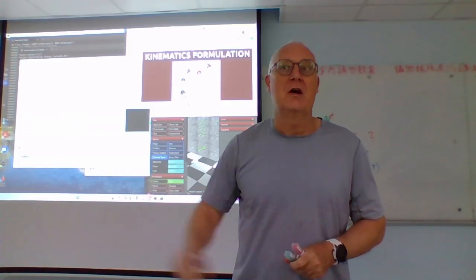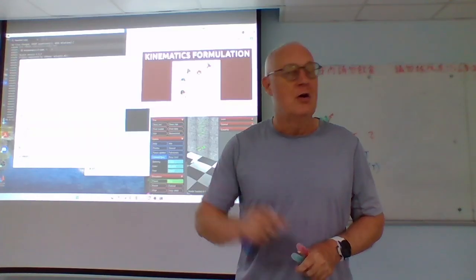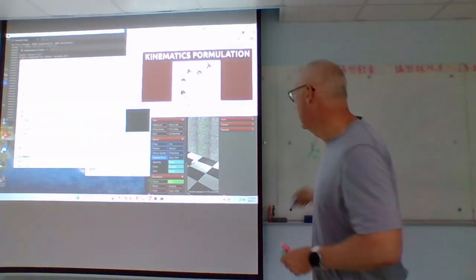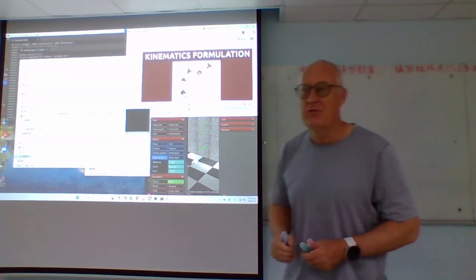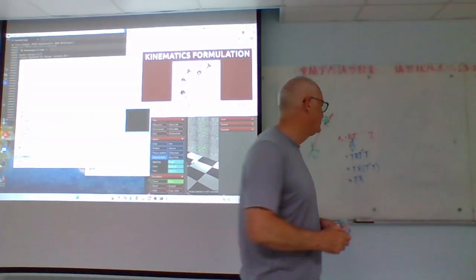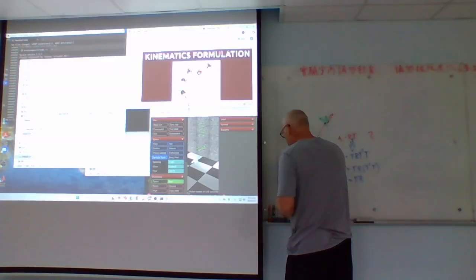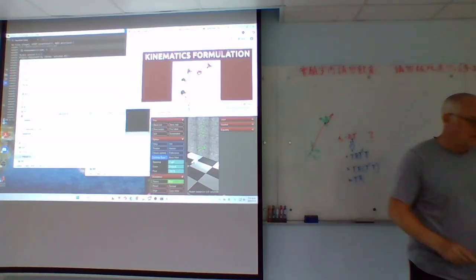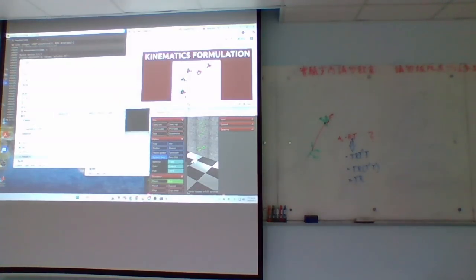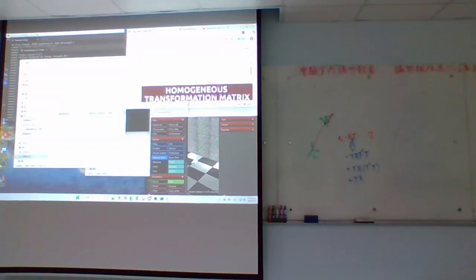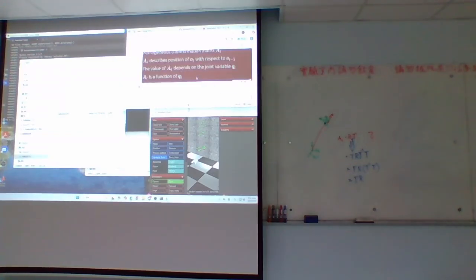Also, those transformation matrices also have to be right multiplied for the same reason as this one. So if you do it step by step, it is not so hard to work out the forward kinematics.